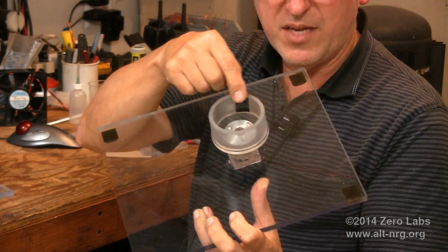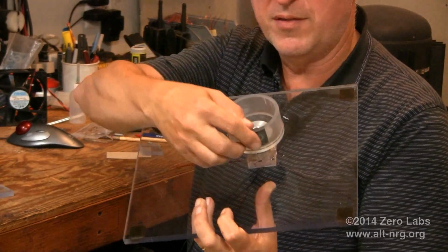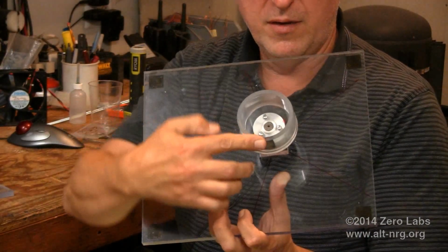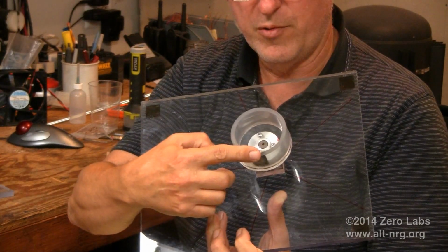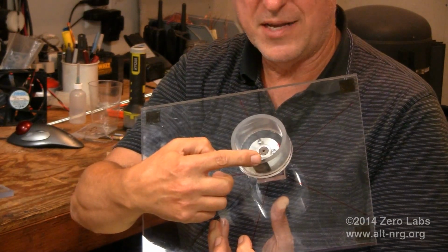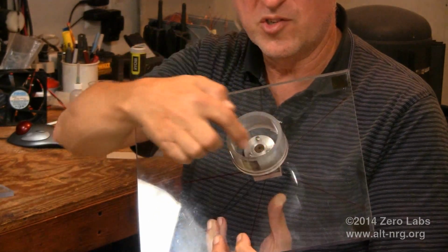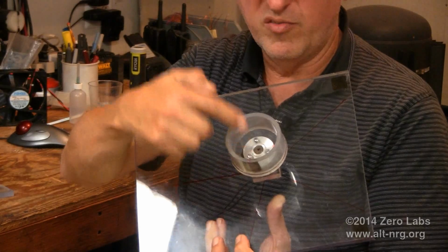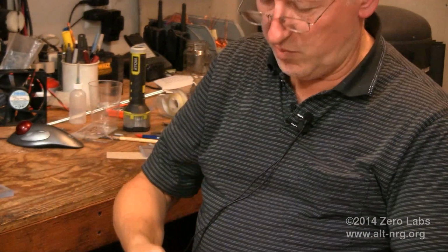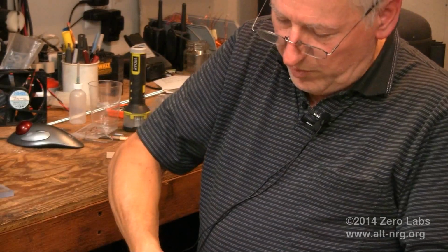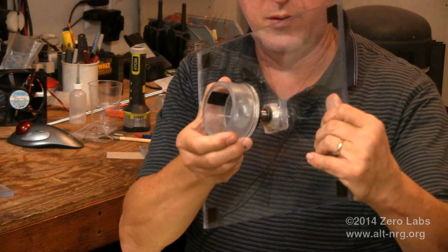This piece of black tape here is actually holding a washer against the side of the drum, because the wall thickness of the drum, which is a cut-off section of PVC pipe or acrylic pipe, is about 15 thousandths of an inch thinner on this side than it is on this side. So even though it's centered, it's off balance without this washer inside. It just sits on the spindle.